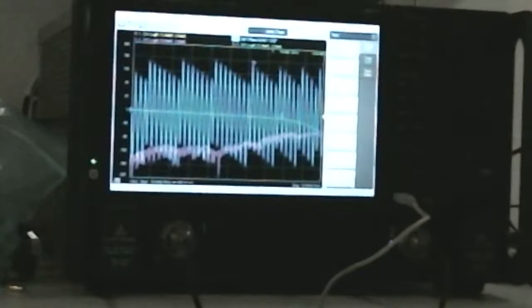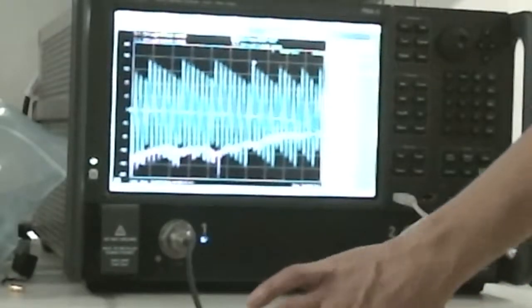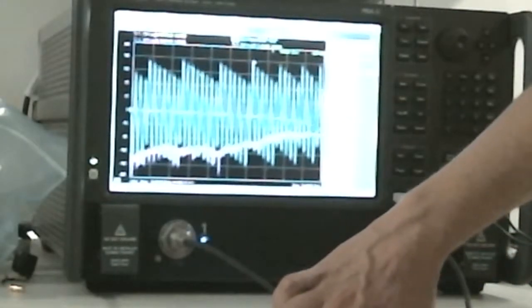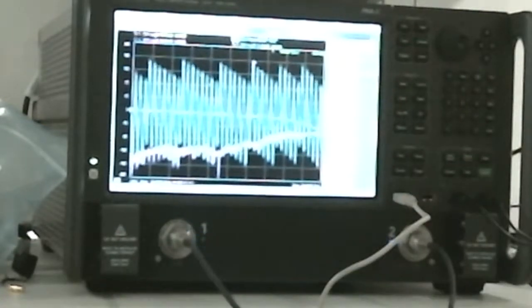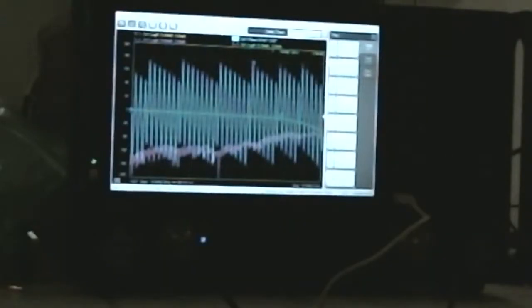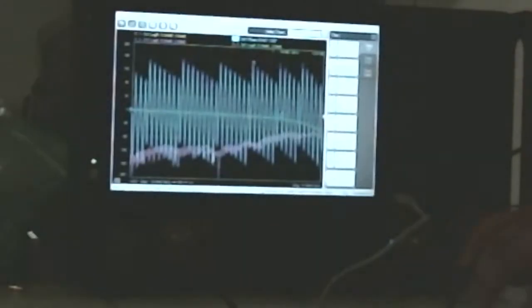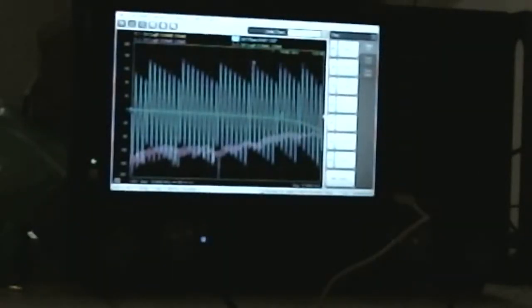But what I want to show you guys is this is the S21, but if I change this, based on moving this cable, you're going to get a different response. So this is why I don't recommend using this quality of cable. For a couple hundred megahertz this is okay, but if you're going to anywhere in the gigahertz regime, you need to have really good quality cables, because if the phase of the cable is changing and you want to measure,